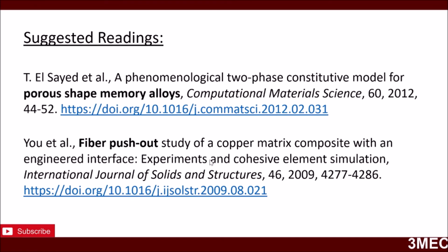Also, as I told you, fiber-matrix interaction is a very important problem. We have done some work in the past on that as well. One of these papers basically deals with that. In this case, it's not shape memory alloys, but it gives you an idea of how you can find out the bonding strength of a fiber with the matrix in your case. So again, you can do simple FE analysis if you can get some fiber push-out curves from experiments or from literature.